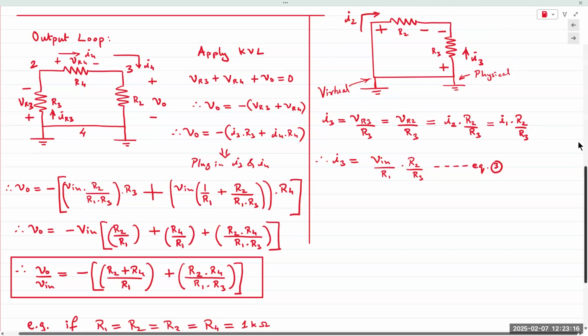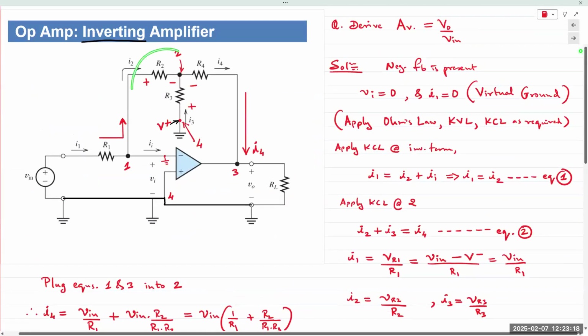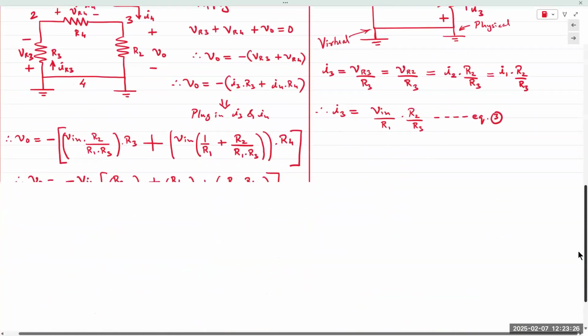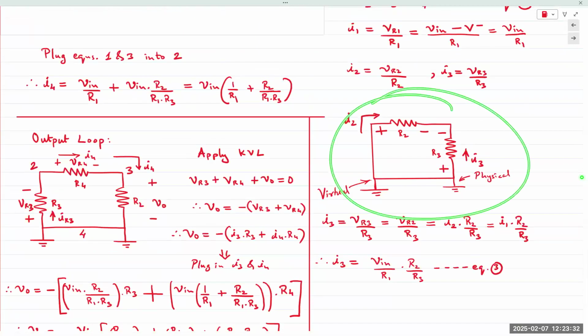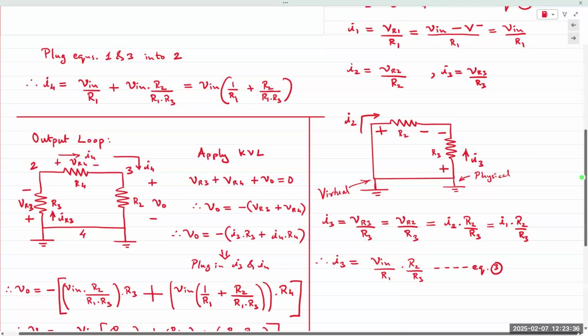If we talk about this circuit right here, then it's obviously not the same. Then it's I2 plus I3 is equal to I4. So technically for this problem, it wouldn't be the same. But I was just talking about this circuit right there. Both are parallel, have the same voltage across it. And if it's the same resistance value, then they would be the same current.